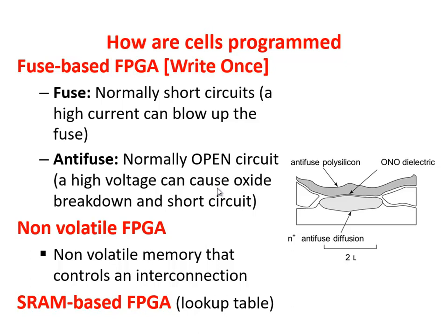Of course, the details of what is programmed is controlled by a software tool which is analogous to a compiler, which starts from the logic description of what you need the FPGA to do, and then accordingly uses the logic that is available. But the way in which the programming occurs can be quite different.